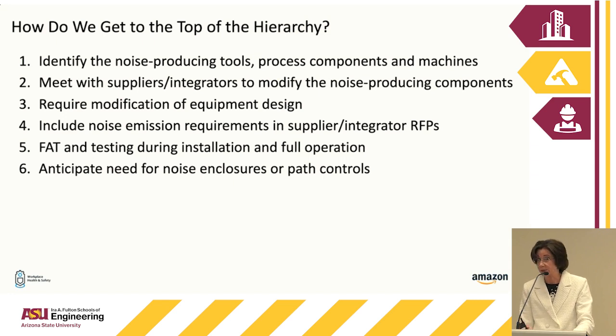For instance, one of the things that I'm doing right now is working with our material handling equipment to change metal rollers in the conveyance system to coated rollers. That's a heavy lift. You think that it's fairly straightforward. Yeah, come on, let's do it. It's a lot of work. And then we have to change them out more frequently. They wear out more quickly. They're not as reliable as a metal roller.